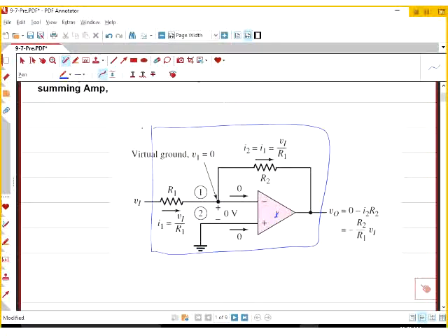To analyze an op-amp, we use 4 rules. First, whatever the voltage at the plus pin is, its voltage is going to be the same at the negative. No current goes to the op-amp. And we're going to use Ohm's law to find what I1 is. And I1 has to be the same as I2. Why? The current coming to the node has to get out.